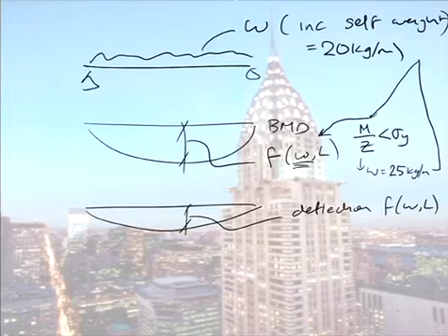So you don't have to redraw everything all the time. You say, here's the new load, here's the new moment, here's the new Z value. And if it's the same beam size, you stop, you've finished iterating. If you then find, oh, that beam's not big enough because I've increased the load, it now has to weigh 30 kilograms per metre, then you have to go in and increase your load again and iterate. Now that sounds very torturous. It's a 1 or 2 iteration process because the beam self-weight is a minor component of the load. So you do that for the moment and then for the deflection as well. You choose a beam size, you go and see what you need. If it's bigger or smaller, you put the new weight in, you stick it into the formula again.